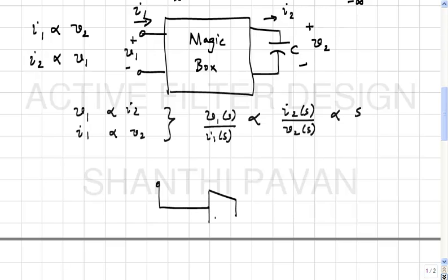This is the notation for a transconductance. Okay. It's understood that this voltage is referred to ground. When somebody says the potential of this node is 5 volts, it is with respect to ground, which is not shown. It's a voltage controlled current source, right? The voltage is always measured between 2 points, the other point is assumed to be ground.